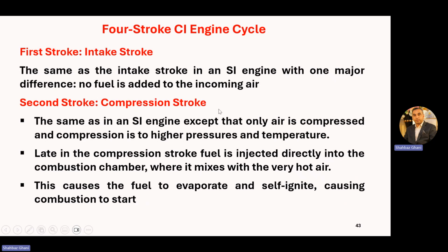Second stroke, compression stroke. The same as in an SI engine, except that only air is compressed and compression is to a high pressure and temperature. Late in the compression stroke, fuel is injected directly into the combustion chamber, where it mixes with the very hot air because of high pressure and high temperature. This causes the fuel to evaporate and self-ignite, causing the combustion to start.